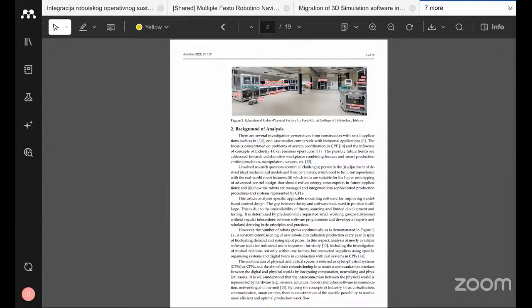What is self-autonomous? Self-autonomous means every module is having their own sensors, their own actuators, their own PLCs, their own control programs, their own inputs and outputs. That's why it is called a self-autonomous workplace. That means every module can work individually. At the same time, it can receive commands from the central factory system, for example, MES.